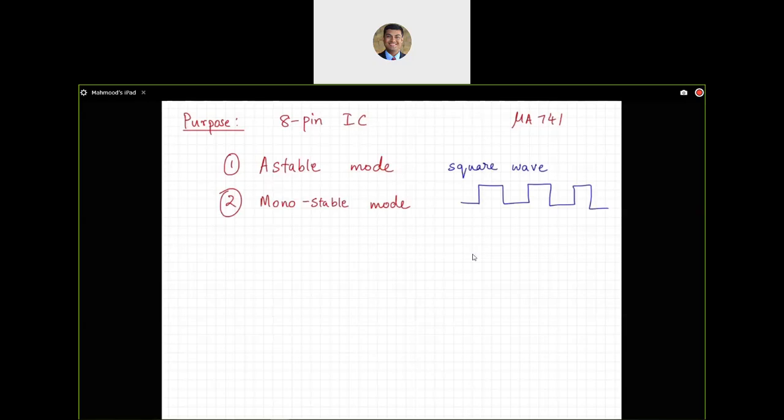And I could use such a waveform to trigger other circuitry to establish timing and synchronization in several modules that I may have in my design. So it's a very useful signal. And in fact, even humans have it, right? The thing that keeps track of time, every human has it, is the heart because it does the pumping at regular intervals. So a timing signal like this is fundamental to a lot of circuit design. So that's what we can do with the astable mode.